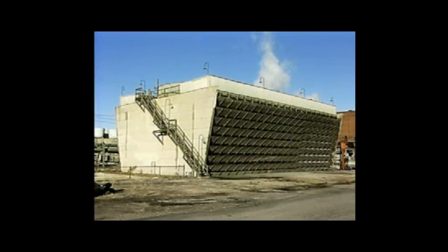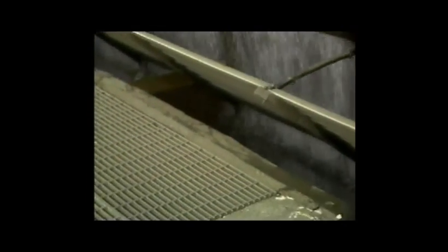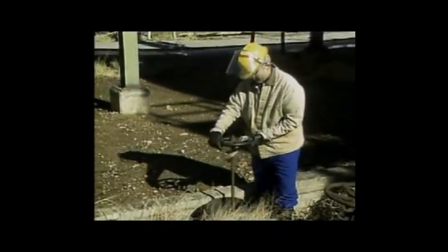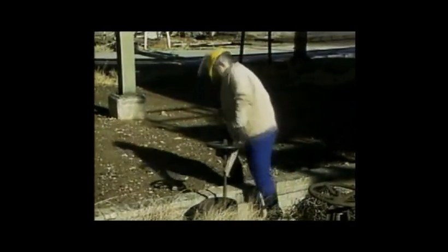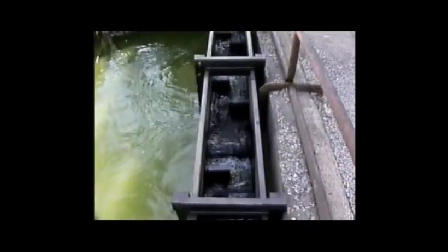Other components, such as blowdown and makeup lines, are also important to a cooling tower's operation. These components deal with the condition of the cooling water. The water in a cooling tower often contains impurities that can cause problems. As the water in the tower evaporates, the concentration of the impurities increases. To control the concentration of impurities, water is periodically discharged from the catch basin through the blowdown line. This water is then replaced with clean water through the makeup line.